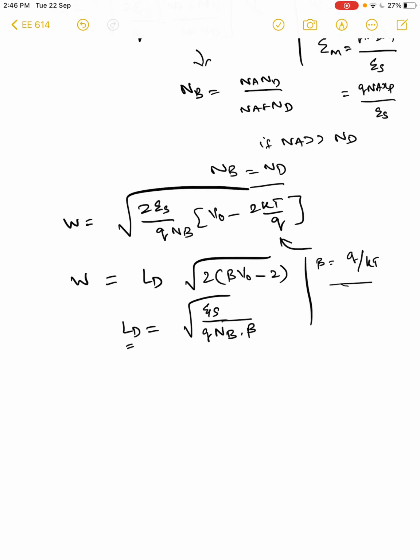Because this is typically seen in any place where you have electric field and charges. The physical meaning of the Debye length is the length at which any potential is screened. So if you have a metal and you have an applied potential over the metal, it is screened within a length extent of a Debye length. This is typically used when you have what is called the Debye equation, where del square V is 1 by L square V0, something of this sort. You can see that this is a differential equation, and it reduces as 1 by LD square, where LD is given by this.